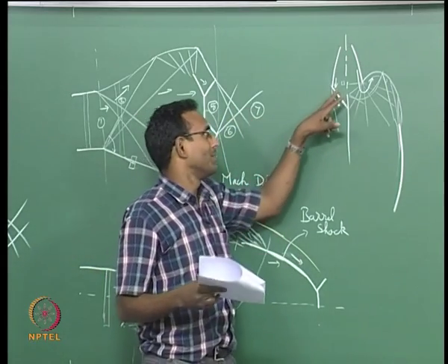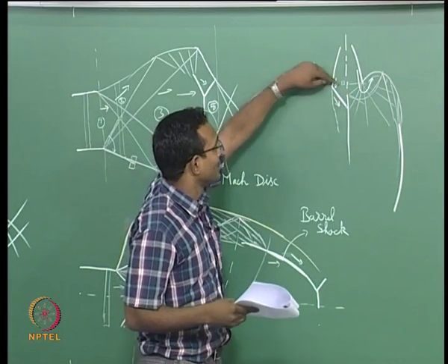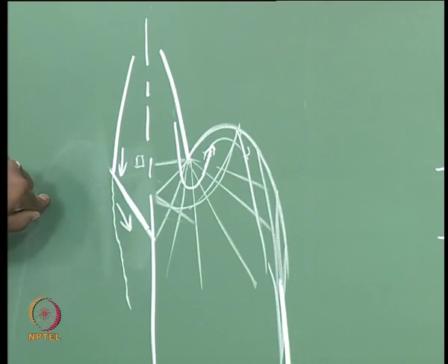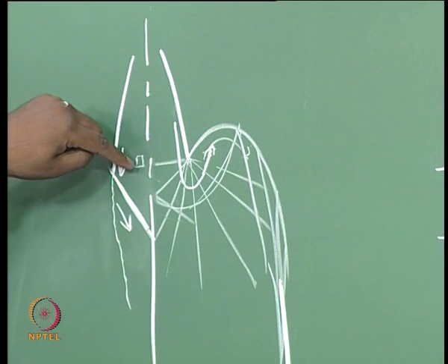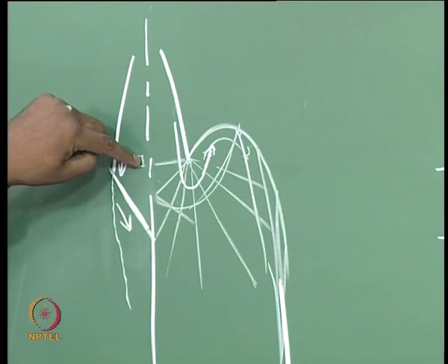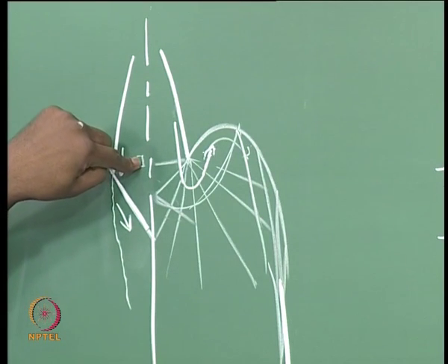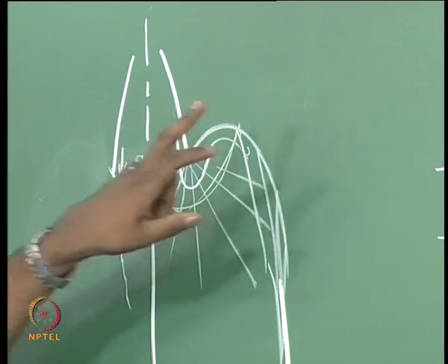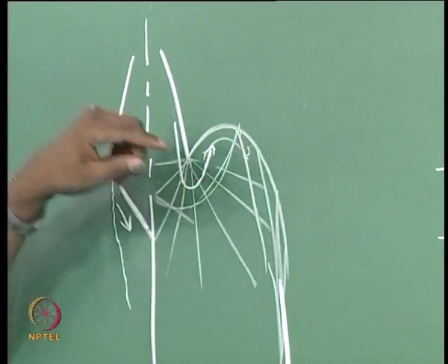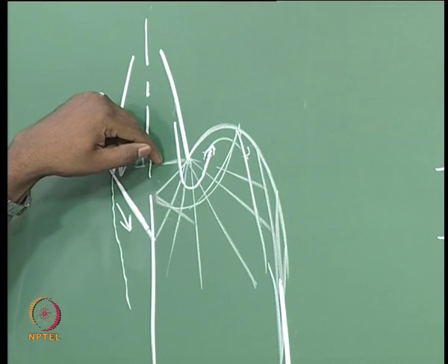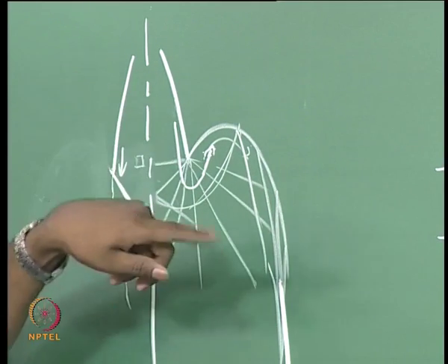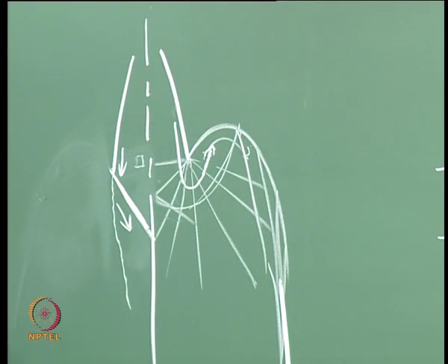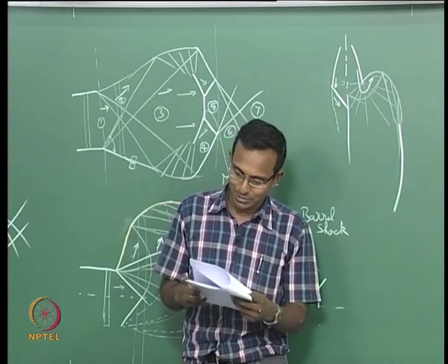Okay. If you think about it, what we are talking about is pressure outside is decreasing, which means initially pressure was very high compared to this pressure, which means I have expanded this fluid too much, so it is over expanded. Later this pressure decreases, and so I end up with this picture. Then I have expanded too little, I have to expand much more after I go out, so it becomes over expanded, sorry, under expanded at that point. Okay. That is what happens out there.